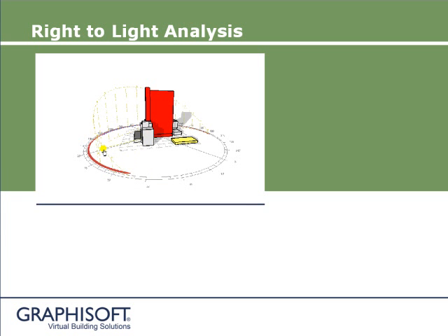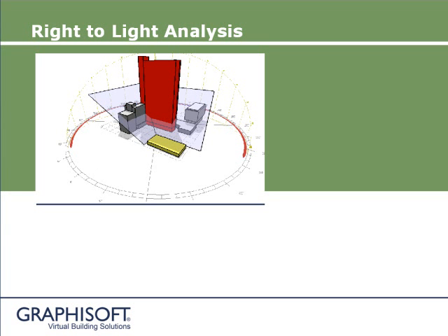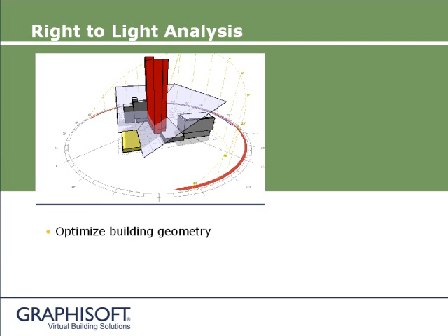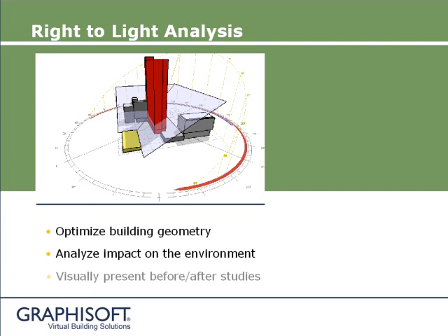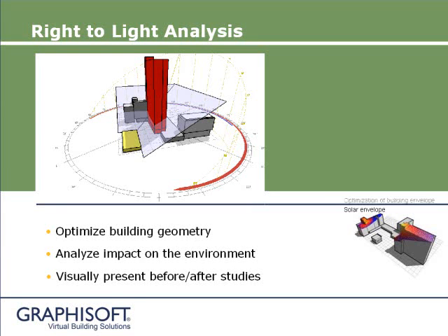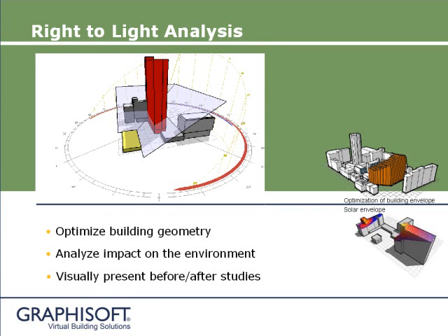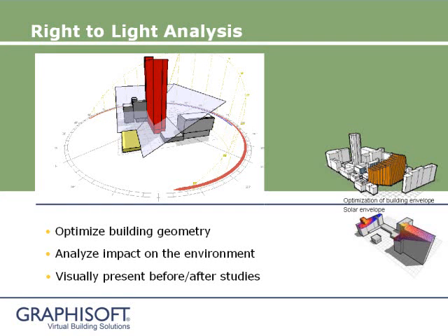You can quickly assess and ensure that your new building meets planning requirements and does not infringe legal rights to light. This is possible very early in the design stage. Using your mass model, you can get site projection angles and assessments of obstructions and define maximum building envelope. Use the results to communicate your design and win over public authorities. These results will mitigate the risk of abortive design or construction works.